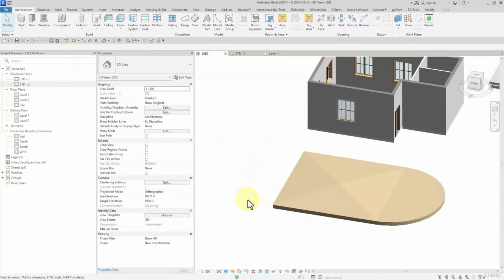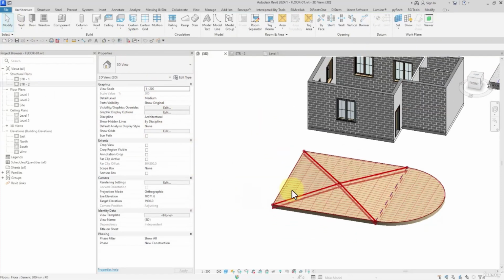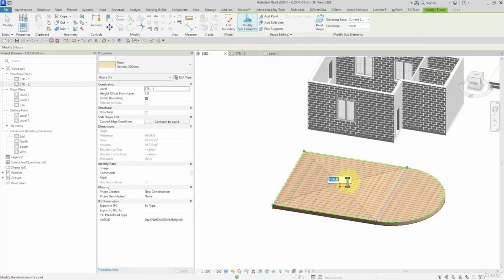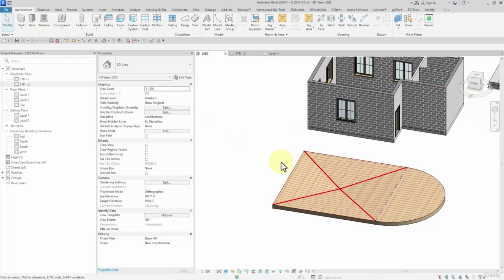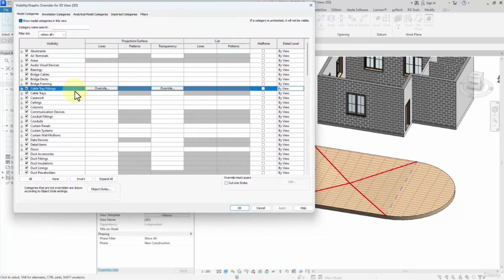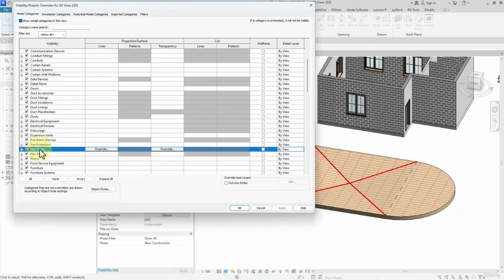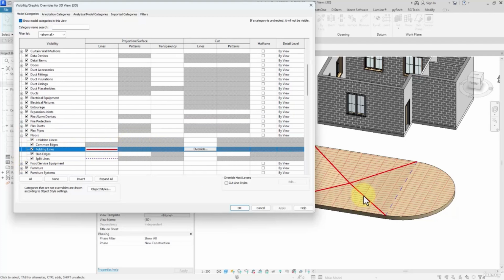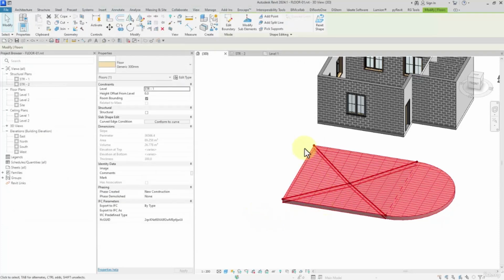As you can see, it is shown like a folding line. Let me specify a negative value, minus 250. Revit enables us to control the visibility of these lines here, or edit the type of the lines or line patterns, watch this, or hide them this way, controlling the color, line pattern, line weight.